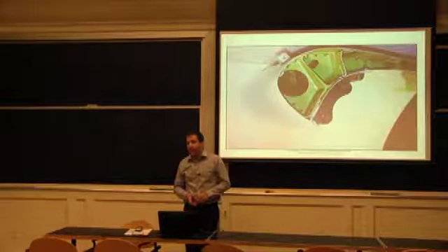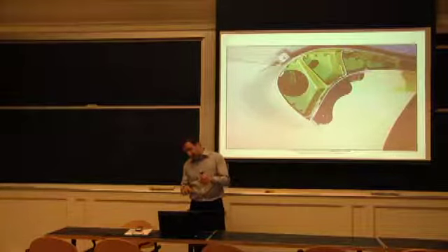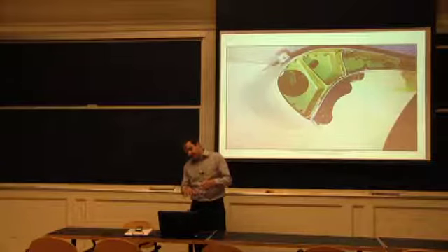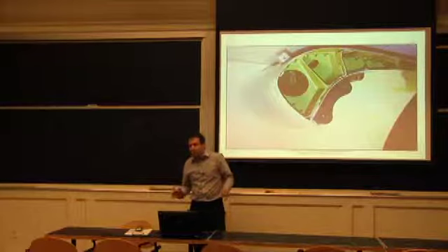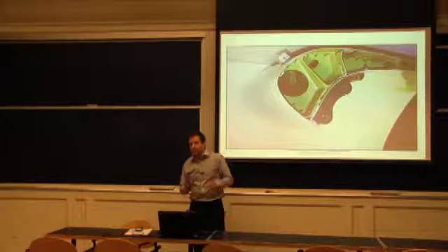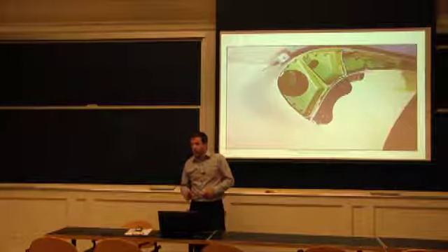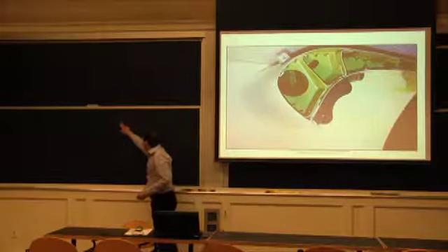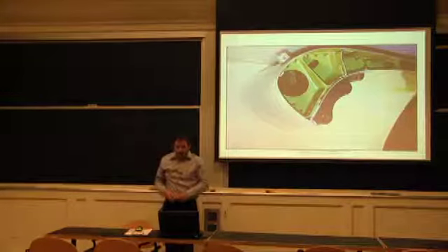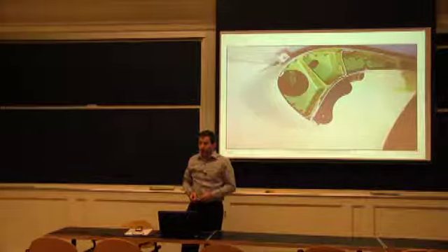And the good news, though, by engineering, when you look at this, there's clearly going to be a side in tension and a side in compression. And the web, we can put holes in it, and it's still fine. So if you have a little impurity in the mold, it's okay. So you had essentially to verify that your top flange was going to have the properties you required.